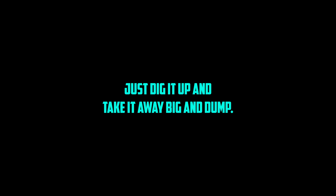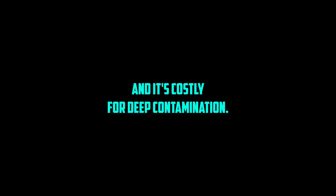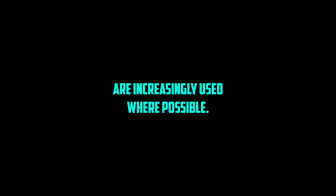The traditional way is just dig it up and take it away, dig and dump. But finding landfill sites is hard, and it's costly for deep contamination. So alternative methods, physical, chemical, biological treatments on site, are increasingly used where possible.